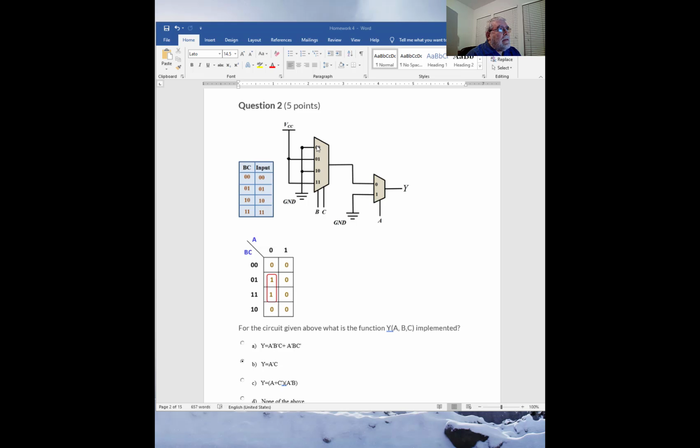That means we have a 0 input here, whereas with 0,1 and 1,1 we have a VCC. So we start doing the same thing as in problem 1. We start changing this and see what input is allocated to go through the output, and then we build our Karnaugh map or truth table.